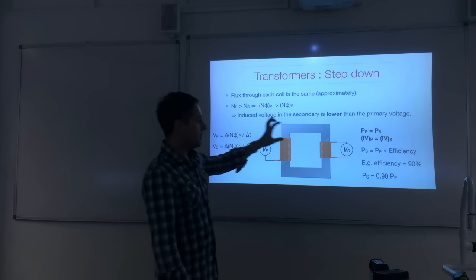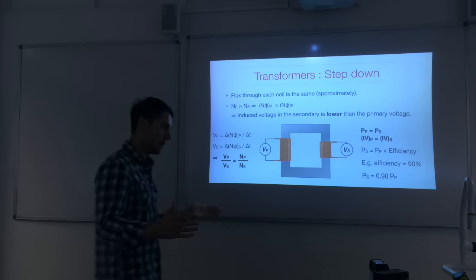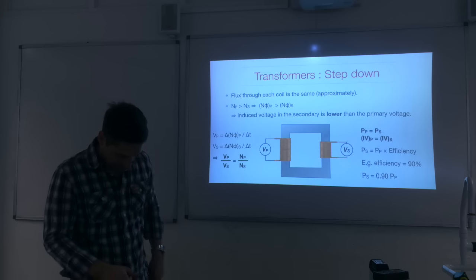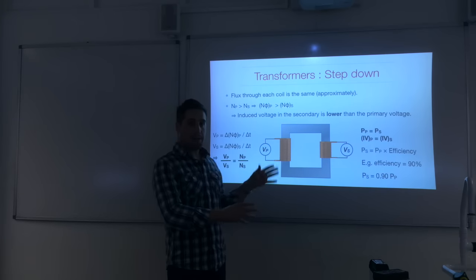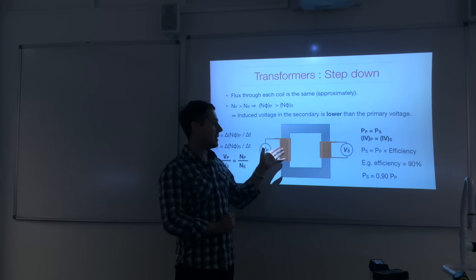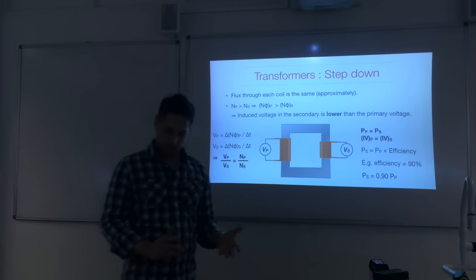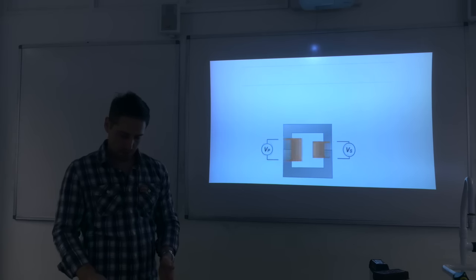So there I assumed that the power was 100% efficient, just so you can see what happens to the current. So the current increases. And the power losses here would be heat predominantly, so heat in the coils. When you pass currents through coils, they get a bit hot, so that'd be the main loss.